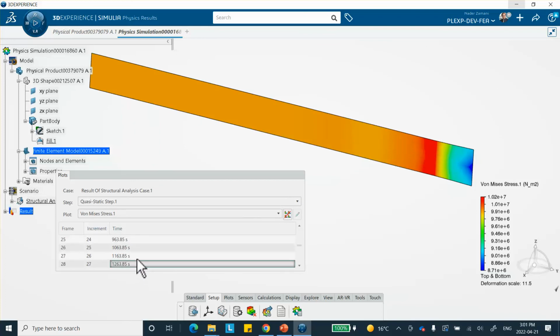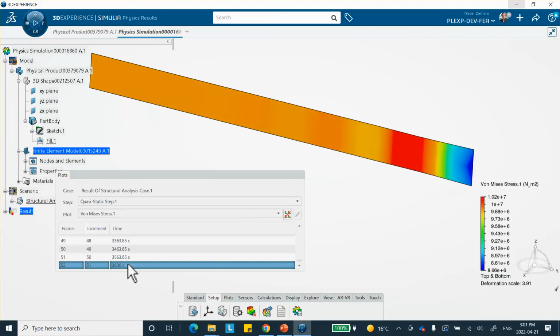The stress is going to be that 10 megapascal. It's not going to change here, but the displacements will. If you put the cursor on it, you see that it's 10 megapascal. You can see that over here, because of the clamp, of course, there is some stress concentration and things like this. Now, when you look at the displacement,